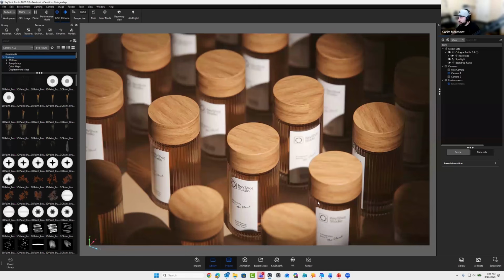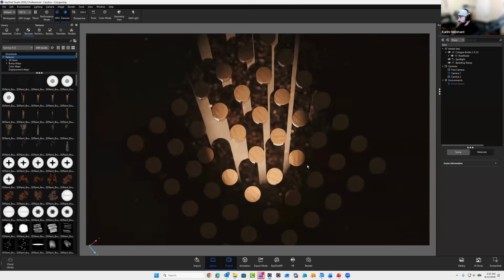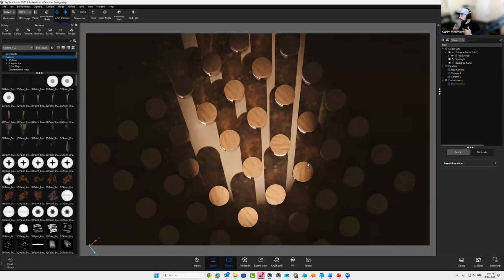And aside from that, if we get a top view, one of the differences between HDRIs and physical lights is the realism of shadow cast. So an HDRI is kind of a flatter environment, and when we're using HDRIs to light things, things look more uniform. In this case, this is very realistic to an actual light source. The farther to the edges of that light source you go, the wider those shadows get casted off to the sides, the angle increases. And that happens when you're using physical lights. It doesn't happen as much when you're using HDRIs. So that little extra bit of realism is, again, going to trick the brain when you're looking at those images to feel like it's an actual image, like a product photograph, rather than a rendering inside of KeyShot.